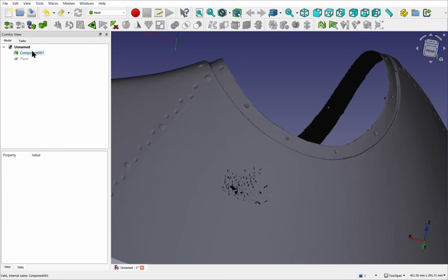When the component is unselected, you can see we've got the tool still available here. So let's click close holes, and there we don't get the flash of the pre-selection of faces, and we can go through and try to close these holes in here. And this is quite a laborious job if you're using this tool. If we've got ones that are quite stubborn, we can use this one and try to close them. A better tool, let's go into this blank space and right click and leave hole filler mode. A better tool is this one here.